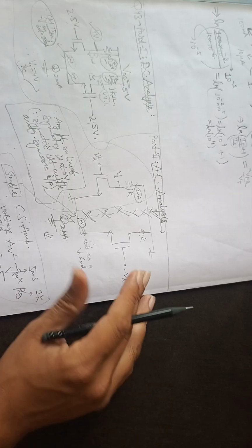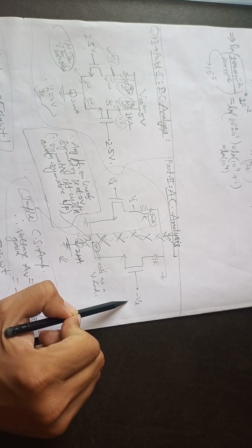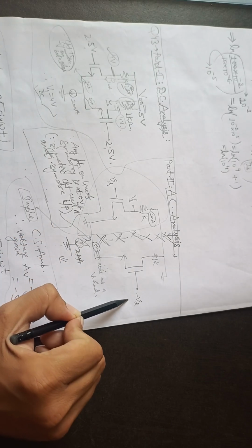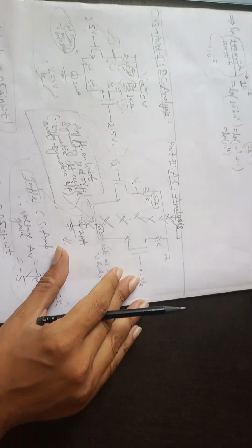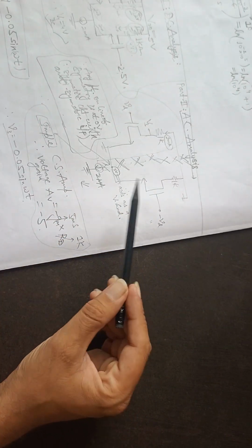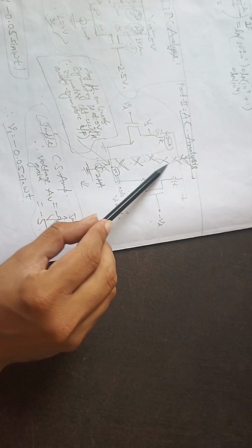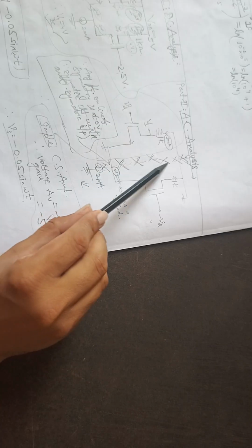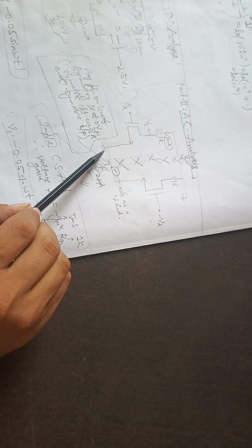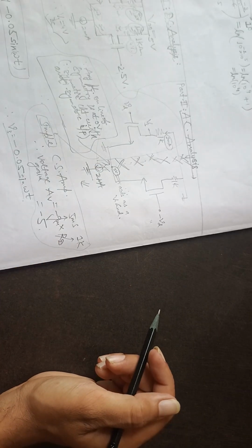we can see that both the inputs are VD and minus VD, because one part is plus 0.01 sin omega t, and the other part is minus 0.01 sin omega t. In such a case, in a differential amplifier, any point on the line of symmetry is at 0 volt. So all these points are at 0 volt. So we can make it ground, and once you assume it as ground, using the half circuit analysis concept,